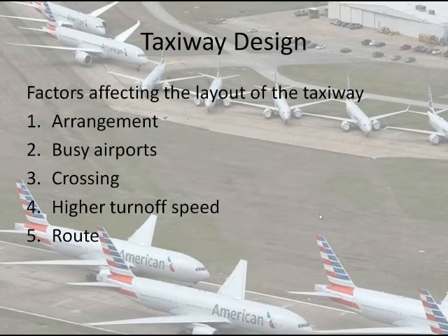Moving on, we are now going to discuss the factors that govern the design of a taxiway. The following factors or considerations govern the layout of the taxiway. First, the arrangement. The arrangement of taxiways should be such that an aircraft which has just landed does not interfere with an aircraft taxiing for takeoff.